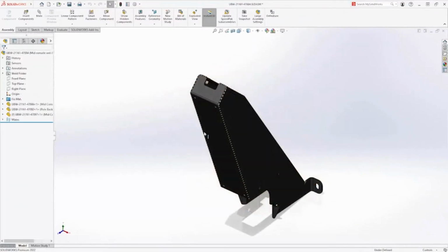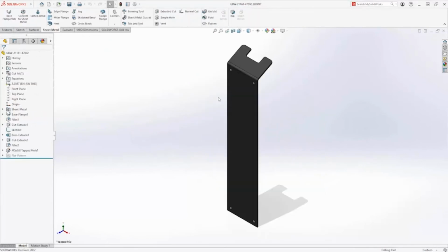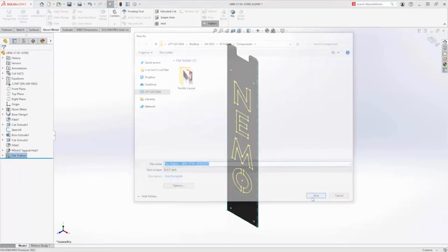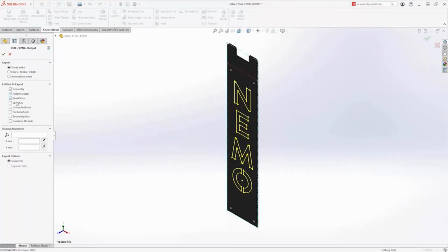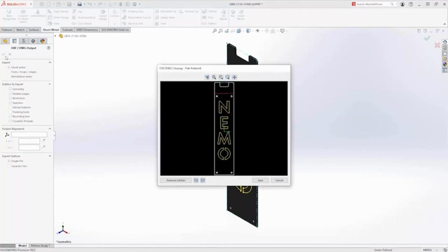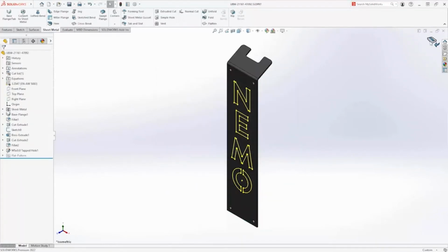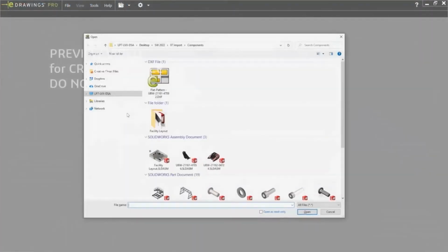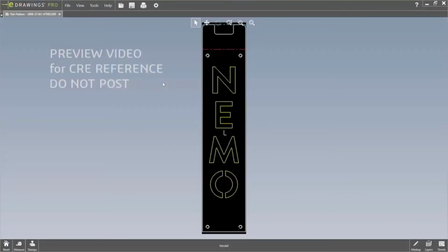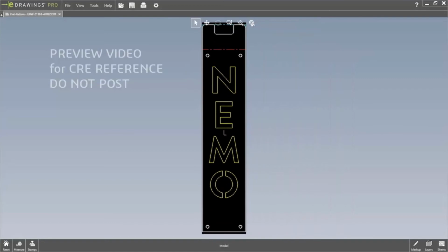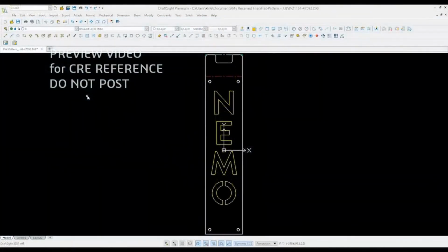Also new in SOLIDWORKS 2022 is the ability to better support the export of DXF and DWG file formats from part files. Components often contain color information that is important for manufacturing processes, such as color of sketches, bend lines, or other information. Now when using export to DXF/DWG from the part file and enabling to include these objects, their colors will be honored in the output of the file. This is extremely valuable for downstream operations where colors can represent different manufacturing processes or parameters for NC tooling equipment. SOLIDWORKS 2022 has improved the way to collaborate with others by improving overall import and export file formats.